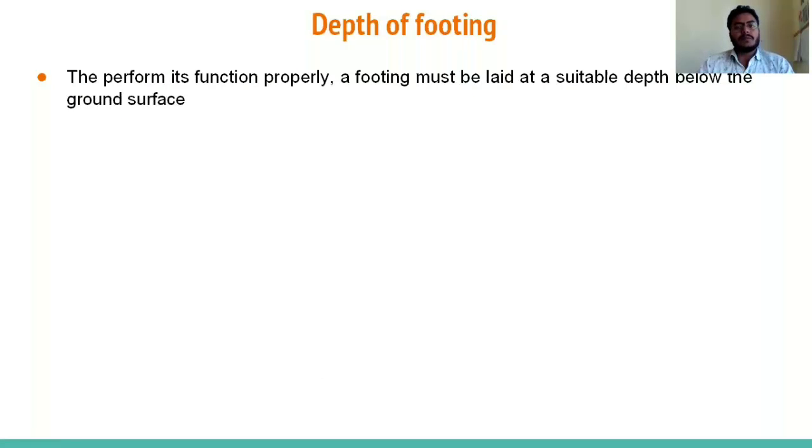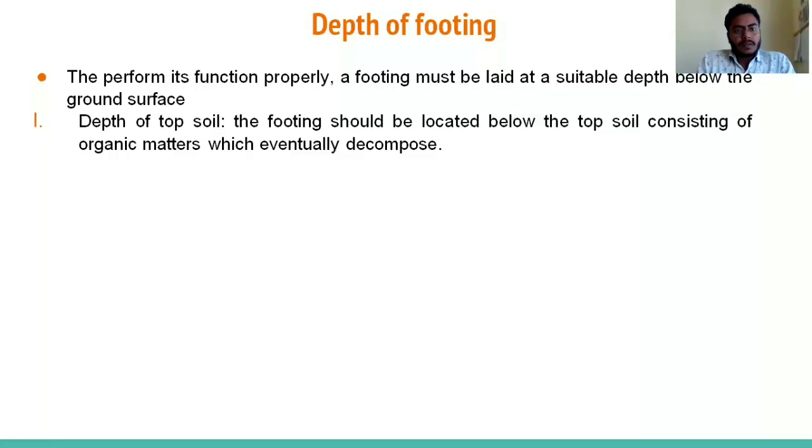So depth of the footing, and that is important to select the depth of the footing. So we have to remove this topsoil. The footing should be located below the topsoil, consisting of organic matters, which eventually decompose. So there are various factors. By keeping all the factors in mind, we have to select the depth of the footing.